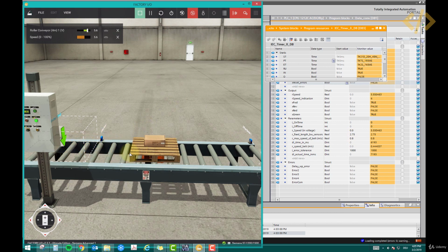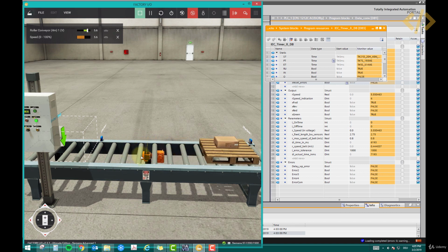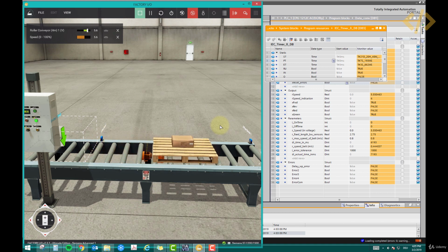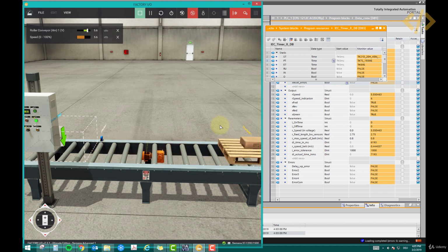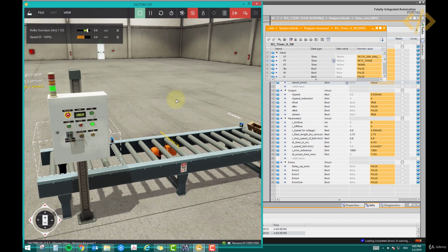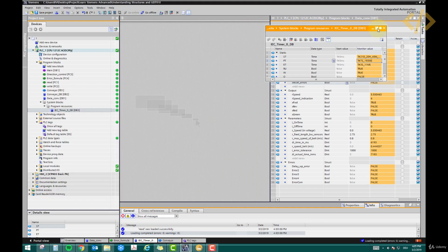So this dynamically changes the tolerance time and the actual time based on the speed of the conveyor. This is a very intelligent way to program your errors, because if you do it in a digital or discrete way, then you have to check how much speed you are giving and change the error tolerance based on the speed. You have a chart and keep comparing it. I have seen people who change the parameter based on speed by moving the tolerance time manually. But in this case, it depends on the speed, yet it is independent of entering it again.